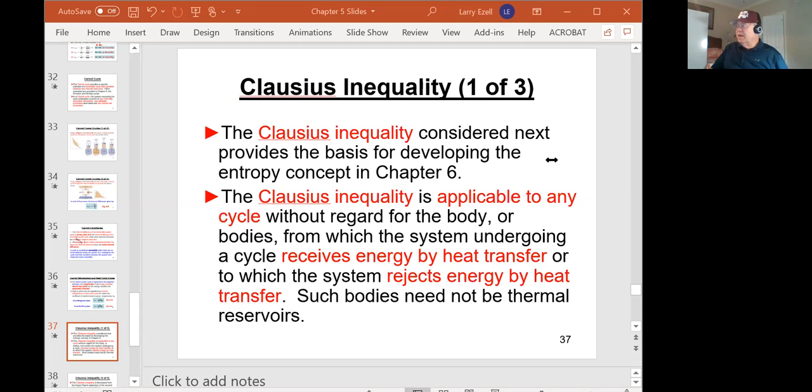But if you don't have gas available like we did in Starkville, then a heat pump is a very good alternative. And the cycle and the heat pump unit is all in one box. I explained how this switching valve switches the flow of refrigerant, and you don't ever touch it. Like in my house, if it was hot on the inside, it would automatically switch over to the air conditioning mode and operate like this.